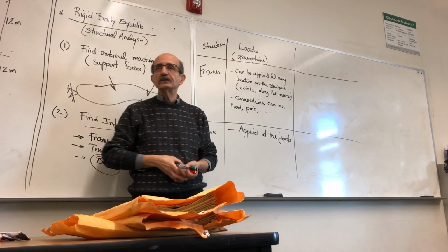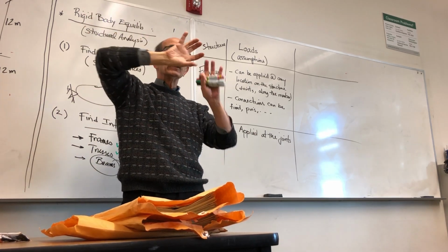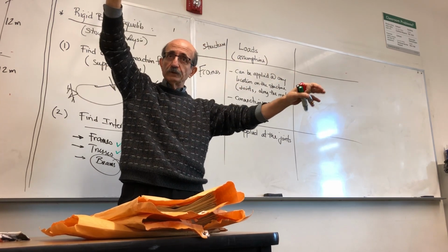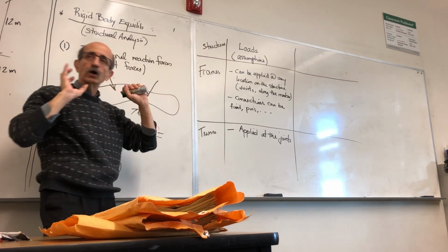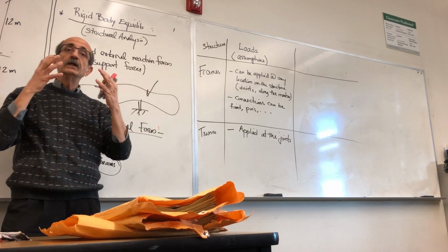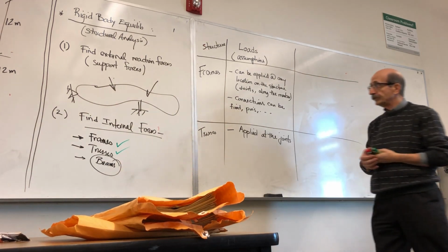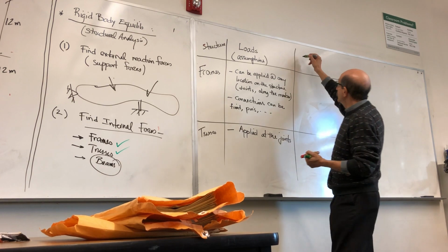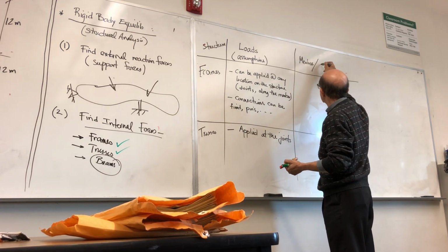We make the assumption that, when it comes to the design or analysis of these structures, the distributed loads are distributed such that part of the load goes to each joint. So the loads are assumed to be acting only at the joints. So that's as far as the attributes when it comes to handling the external loads of the structure, okay? But then, how about members and connections?